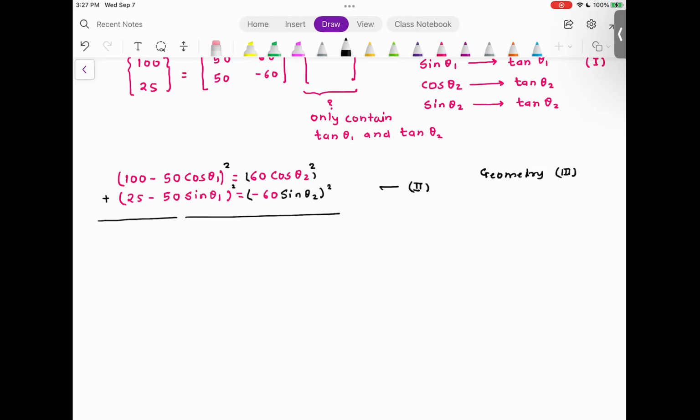So typically, if you want to build an articulated robot that can give you this 6 degrees of freedom solution, it needs to have 6 independent joints. Which means you would have theta 1, theta 2, theta 3, theta 4, theta 5, theta 6, and this 6 degree of freedom robot will give you the wrist or the end effector position and orientation. Everyone understood this? If you decide to solve the forward kinematics problem for this 6 degree of freedom robot, no problem.